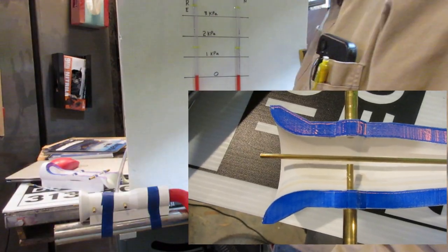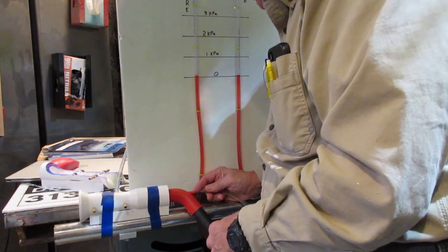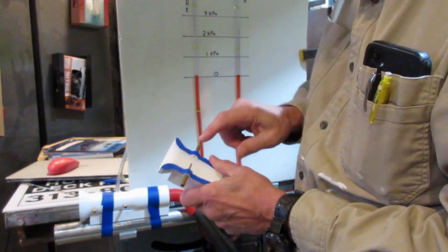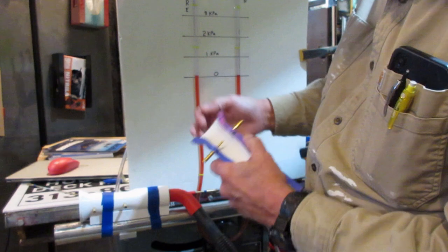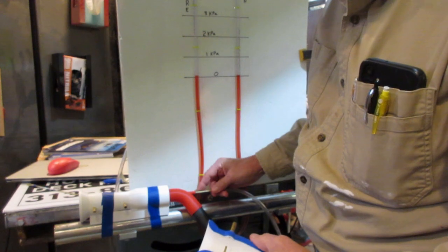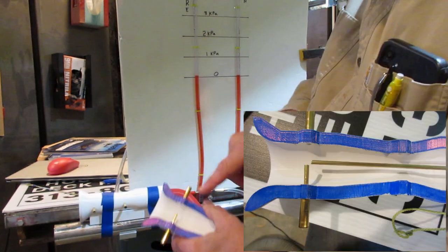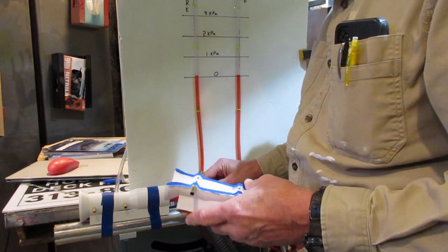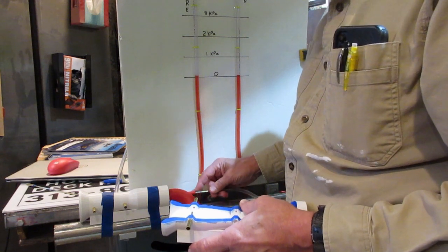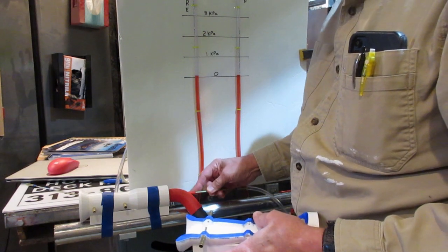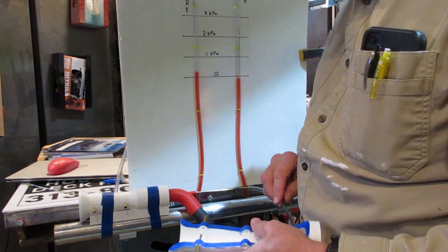So there's our pitot probe, which is just a tube open on the front, and we'll start out by pushing it all the way forward so it's sticking out the front of the Venturi, and we can see that the pressure is 0. And when I pull it back into that curve area right there, still no change in the total pressure or pitot pressure. Pull it back to the first probe right about there where my finger is, still 0. Just checking it. We can pull it back a little bit further to the throat of the Venturi, and again our pitot pressure or total pressure stays 0.